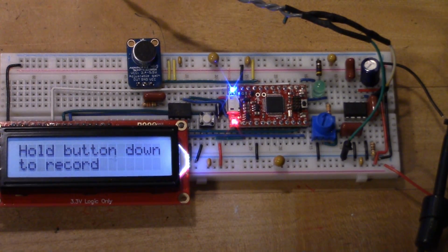The foreground program, the finite state machine, is still looking to see what the user is doing. If the user presses the button, for example during playback, it sets a flag. The interrupt service routine sees that flag. It marks the recording as erased, basically by saying there's 0 bytes stored. They're not actually erased from the RAM, and we go back to not having a recording.